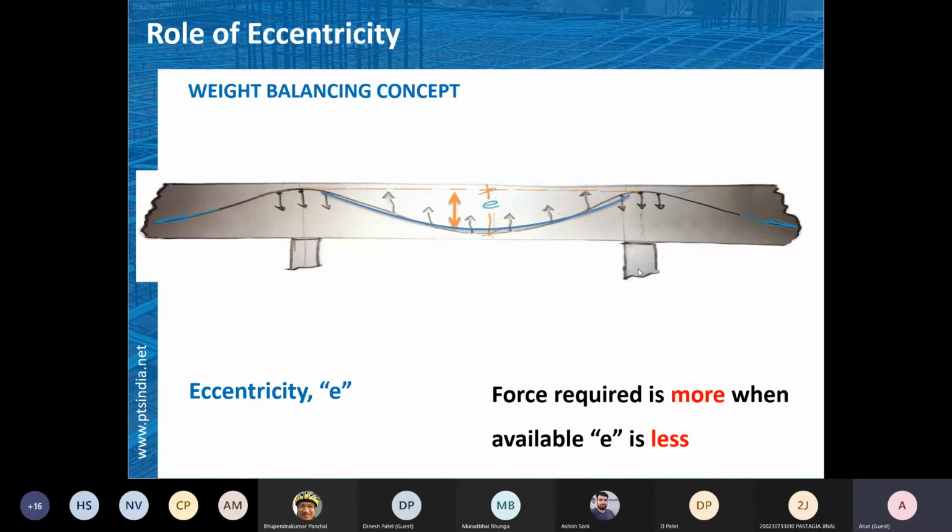In our case, we are not getting much eccentricity because of the thickness constraints. The client, whether an architect, a consultant or a developer, all want thinner elements, the thickness of the slab or depth of the beam to be as minimum as possible, so that they get the benefit of working height or overall height of the structure. So here, we need to play with this eccentricity.